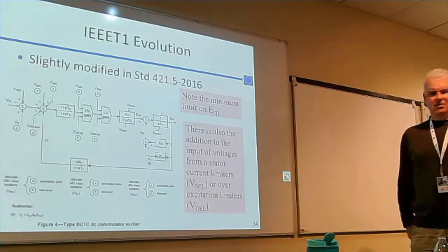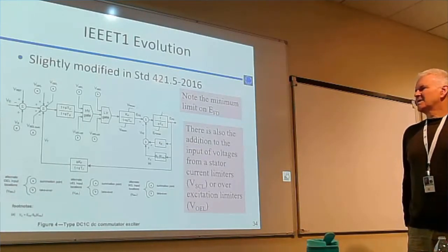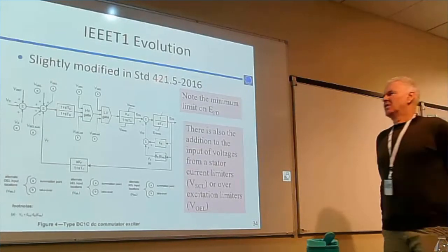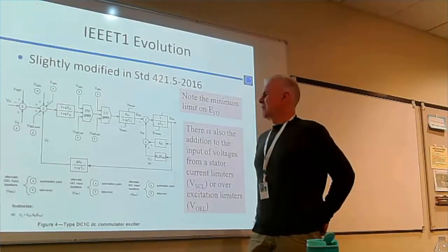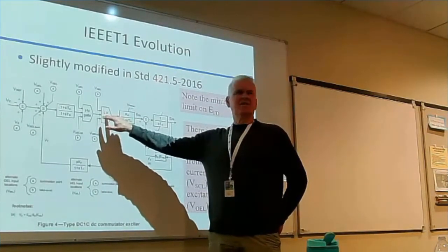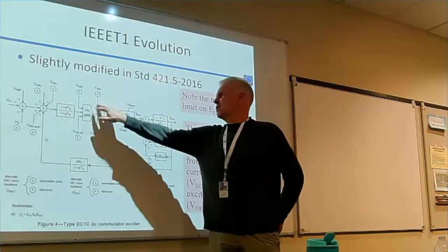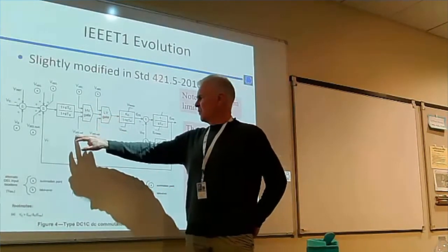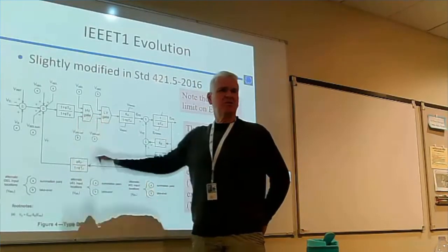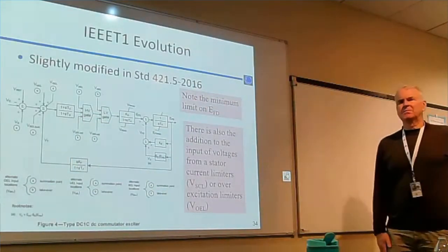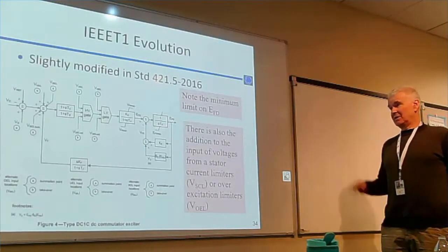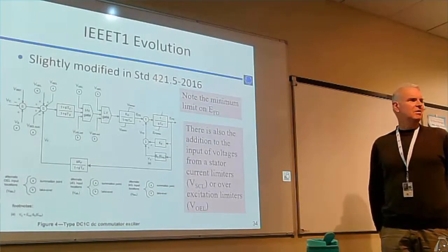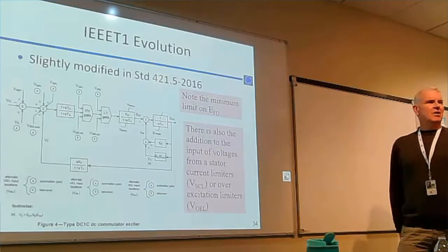Tom, those symbols labeled HV gate and LV gate are the high value and low value gates. Maximum select, minimum select? Yeah. This just says either a max or a min. Take the low value. You've got two inputs coming in, pick the low one. Actually, I guess you've got three inputs coming in. This one says take the high value coming in. So that's a high value gate and a low value gate. High value gates take the high value coming in, low value gates take the low value coming in. Okay.